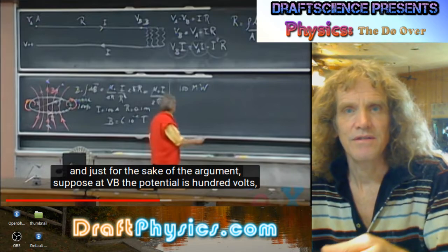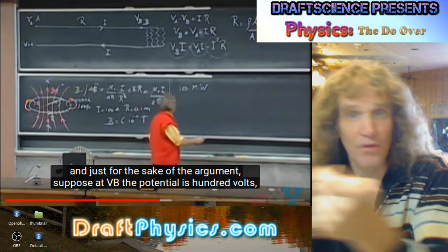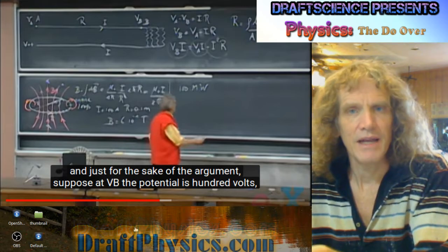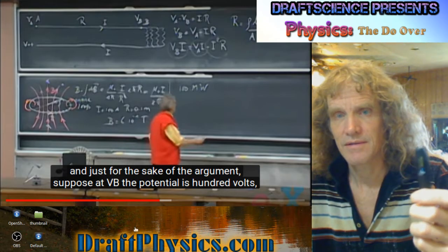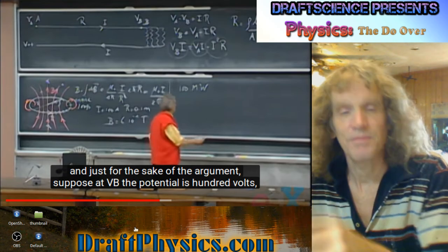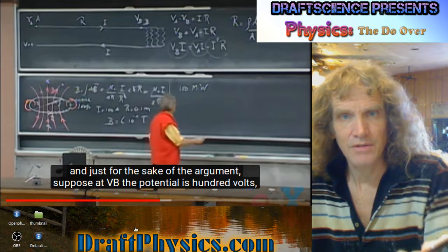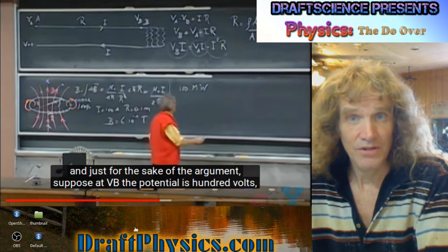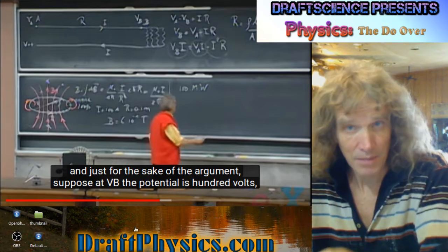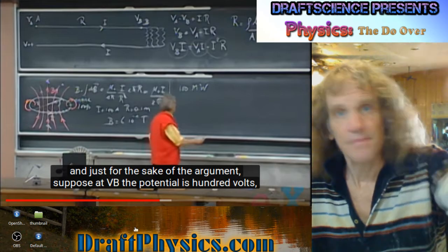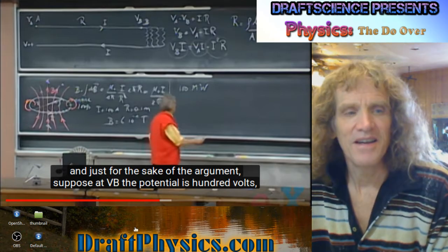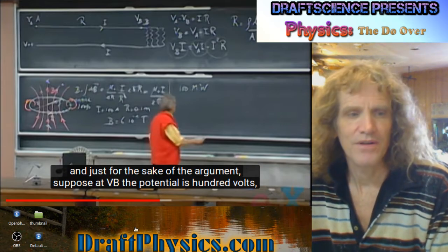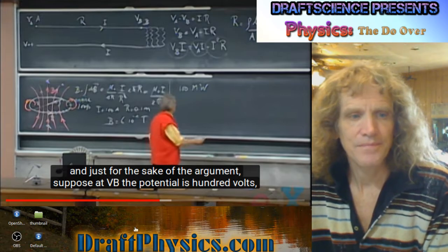And so you encounter the resistance, the more exchanges you make. So if you're at low voltage making lots of exchanges through the wire, you have more opportunity to create heat. But if you have high pressure, that is high voltage, then you have to make fewer exchanges because you're exchanging big bills, $10,000 bills instead of dollar bills. So you can transfer a lot more pressure a lot more efficiently with a high voltage. The downside being the high voltage spreads to the rest of the environment a little too easily. It goes through other conductors too easily, like the atmosphere. So you can't go too high.